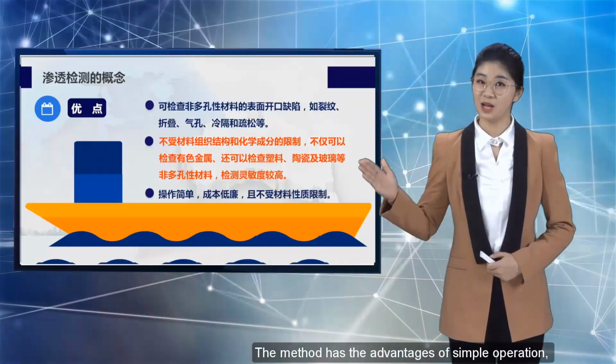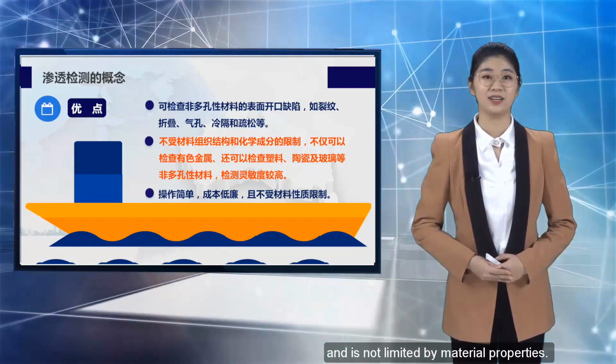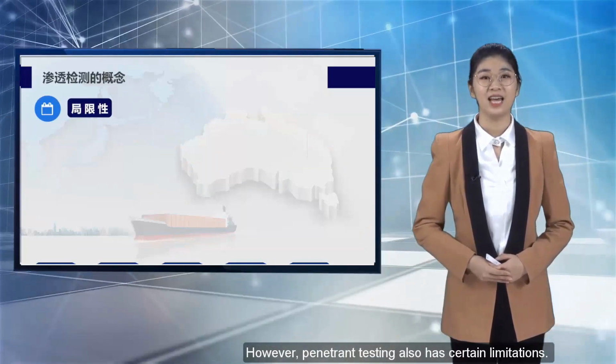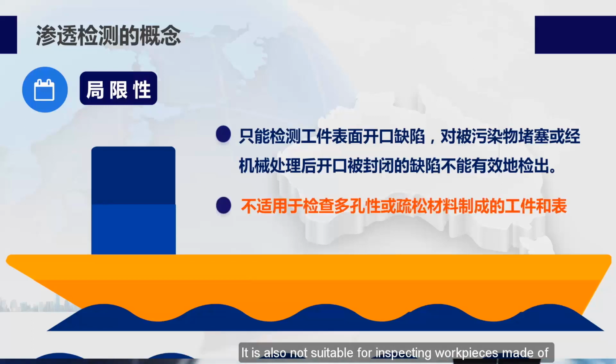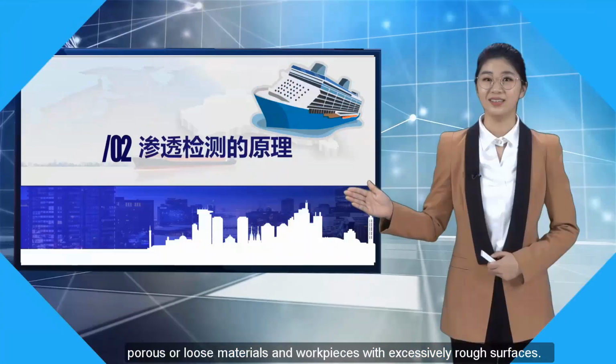With high detection sensitivity, the method has the advantages of simple operation, low cost, and is not limited by material properties. However, penetrant testing also has certain limitations. It can only detect the opening defects on the surface of the workpiece, and cannot effectively detect the defects that are blocked by pollutants or the openings are closed after mechanical treatment. It is also not suitable for inspecting workpieces made of porous or loose materials and workpieces with excessively rough surfaces.